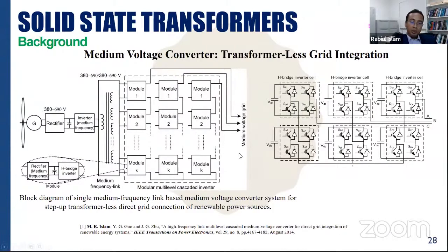Okay, as I mentioned to you before, this type of converter, the left side circuit, right side circuit, this is the cascaded modular multi-level converter. As I mentioned, this converter is without any diodes, auxiliary diodes and auxiliary capacitors. That's why this one is more suitable. But the only problem is it requires multiple isolated DC sources. So then how to use this type of topology for renewable energy applications or for grid integration of renewable sources?